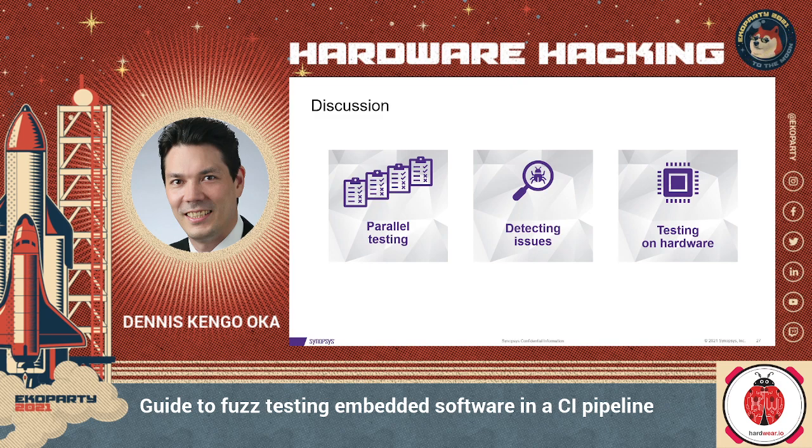The third thing here also to discuss is that while we can perform a majority of testing using software only, there are some testing that requires hardware, especially if we want to test the lower layers of some of the communication protocols, for example, on Bluetooth or CAN, then we would need to have a hardware dongle or a hardware component where we perform testing. But it's important to note that we can perform most of the testing in software and then have just a reduced scope of testing using hardware so that we can be as efficient as possible.